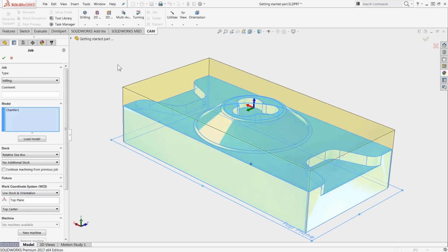This is where we define how our model's XYZ is compared out at the machine. See, at the machine it's pretty defined what is up and down, left and right, but in the CAD world there's no rules. You will receive models from engineers and designers where they clearly missed what was up and down on the model. Second thing we will do in the job is to define where we are going to pick up the part out at the machine. This process is pretty easy. First, always just start from the top and work your way down.